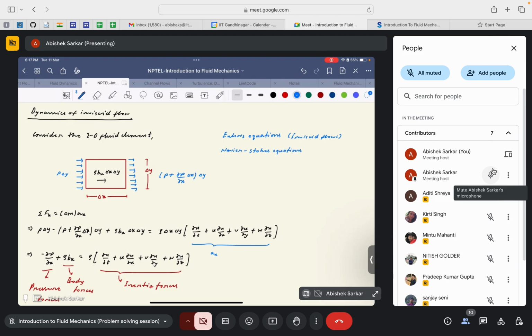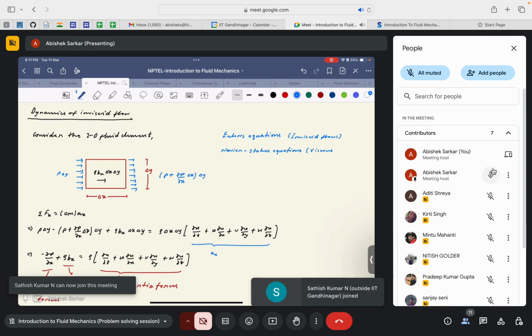Since we already know that the concept of zero viscosity is not practical, because there is no fluid in the world that has a viscosity of zero. All the kinds of fluid flow that we see have some finite viscosity, because of which the velocity gradients are generated, and we inherently feel the motion of fluid over our skin, or the drag because of the fluid motion over, say, an aircraft or the vehicle that we are traveling upon. So we feel the presence of fluid, and that's inherently because of the presence of viscosity.